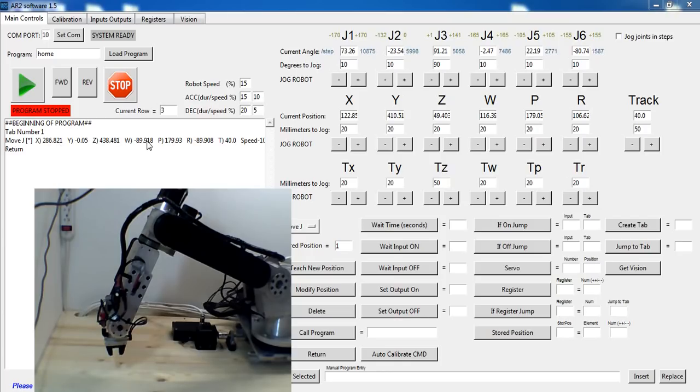So a couple things come with that. If we look at this move and scroll to the end of it, there's a $F at the end. Previously, in the kinematics, I was cheating a little bit. Now that I'm just using the raw kinematics to calculate the position based on the XYZ, yaw, pitch, and roll, we get into something called configurations. Robots have to have configurations to track where they're at, because in certain conditions, for example, if you've watched my set of videos on robot kinematics, this will make more sense.